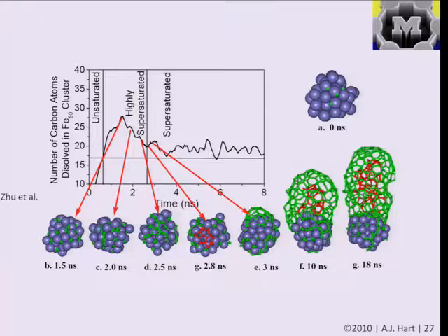So we're seeing here how we can treat the particle for growth of an individual nanotube in the same qualitative way that we're going to treat a whole reactor for growing a large number of nanostructures or a large number of nanoparticles in parallel. And as we've seen before, and we'll see more later, depending on the size of the particle, you might get a single-walled nanotube, or you might get a multi-walled nanotube where you have one structure in the center and another wall on the outside. And if this were bigger, you might have many, many more concentric walls.